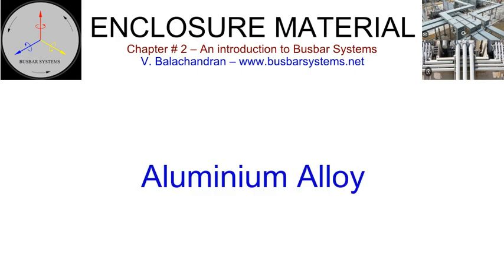Aluminium alloy. Over the last few decades, aluminium welding technology has vastly improved, bringing down the cost significantly. Furthermore, the cost of the dies for extrusion of aluminium has drastically come down. Aluminium sheets are available in various alloy compositions, and it is possible to select a specific alloy for the desired application. Alloy sheets are available with a conductivity of 61% IACS with less mechanical strength to 30% IACS with 60% of the strength of steel. Alloy sheets are available with excellent resistance to corrosion. This flexibility has made aluminium sheets and extrusions the preferred material for bus enclosures.